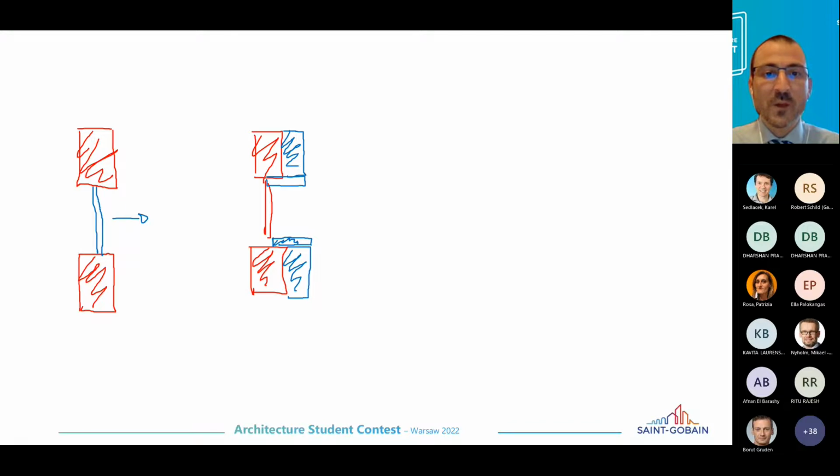Now, the reason for putting this insulation here is very simple, just to avoid the thermal bridges. Yeah? But still, as you can see also from the drawing, most of the time you do not have sufficient thickness here to put the same amount of insulation like we put on the standard wall. You will put maybe 2 centimeters. Then this is a thermal bridge, and it can also generate some issues with condensation if it's not sufficient.